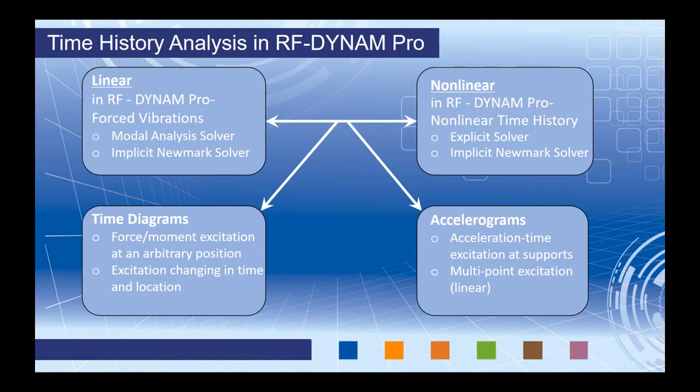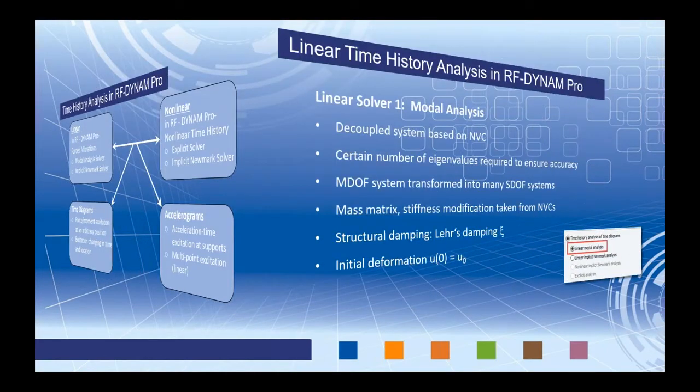Now, regardless of whether you're running a time diagram or an accelerogram, the results are available on a time course monitor, and this is certainly something that we'll be taking a look at quite a bit today. We can export the results into load cases for single time steps, so you can actually see the response of your structure at each individual time step back in RFEM, or we can export a result combination for the result envelope.